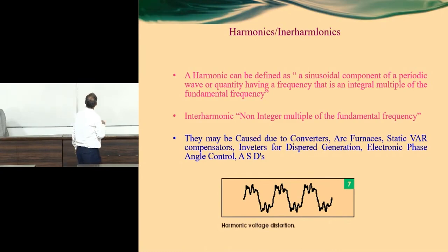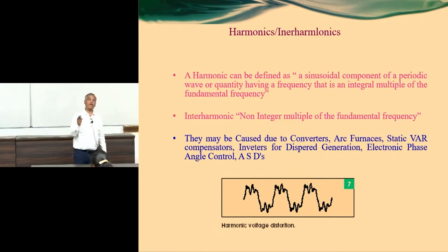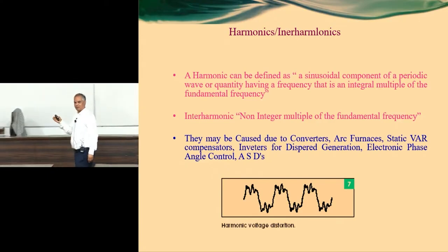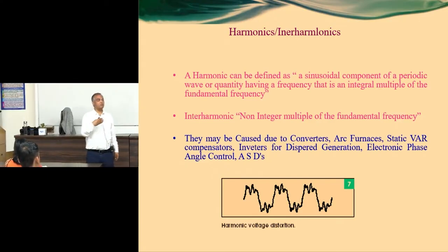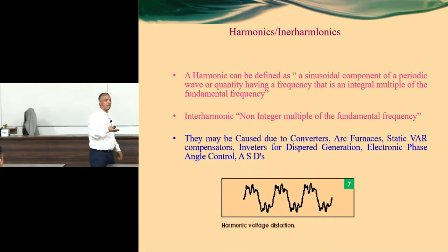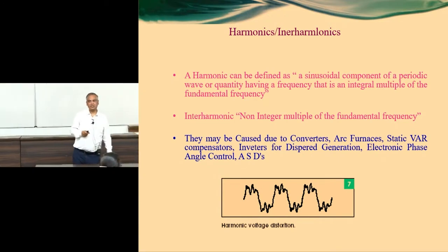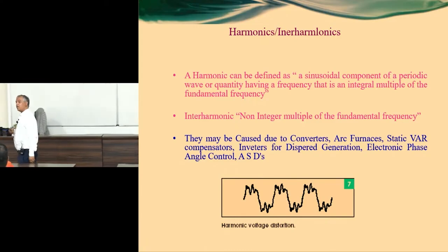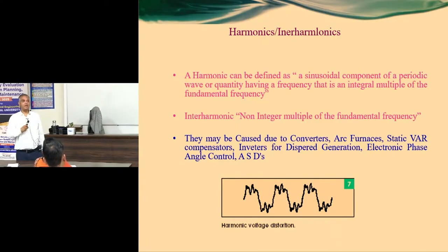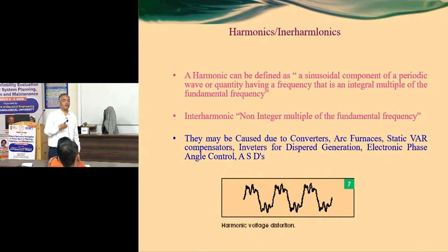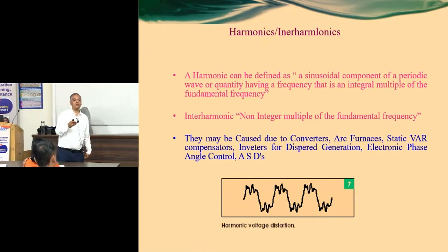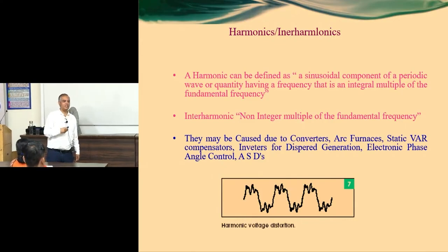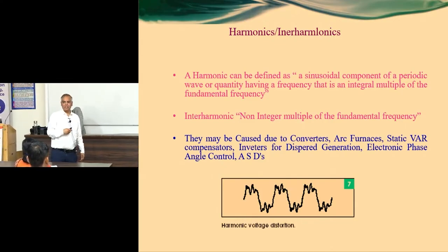Then you have the interharmonic problem, not only harmonic, interharmonic. Harmonic means integer multiples, and those which are fractional multiples of the fundamental are known as interharmonics. So interharmonics are also coming into the picture. Interharmonics may be more dangerous than harmonics, because it is very easy to design a passive filter for harmonics. But how are you going to design it for a fractional frequency? So that is also one of the issues.